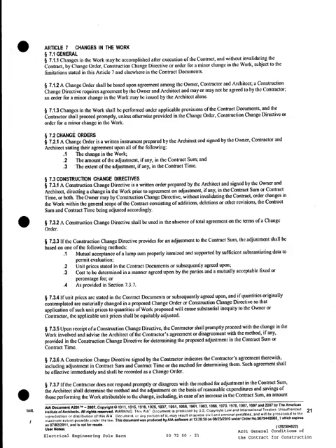And sometimes there'll be a change order on the work that doesn't cost anything, but we still need to document it because it may still cost some extra time. It may not, but you still want to document it. Even if there's no cost and no time involved, you need to document that we changed this, this is what we did, so that it protects everybody.